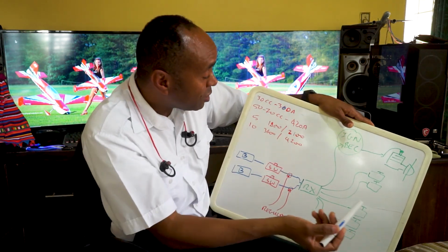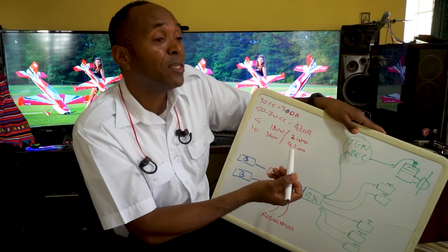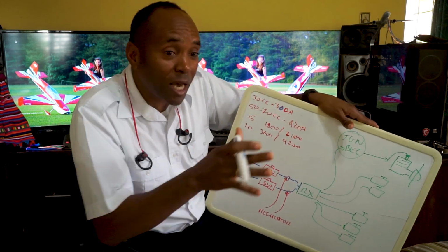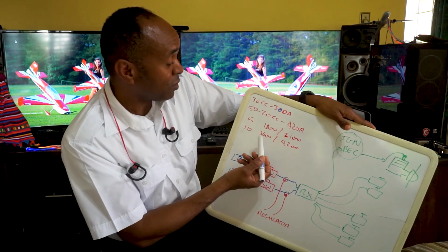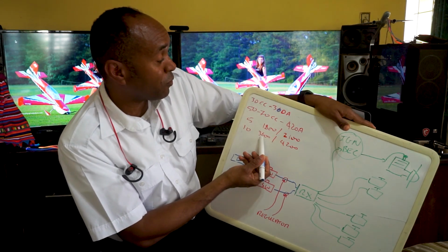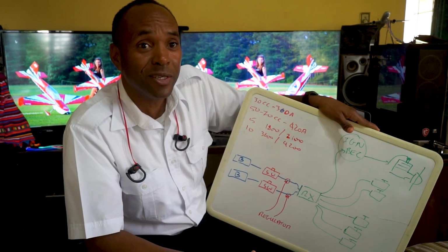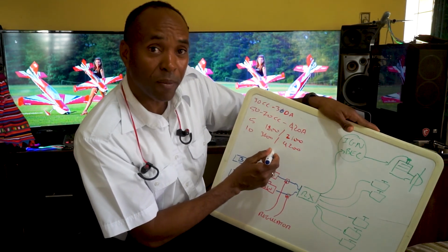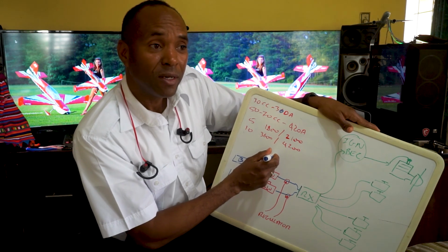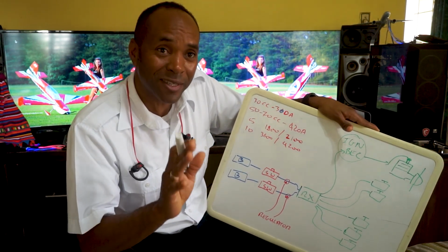With a 70cc airplane it will be 2100 milliamps for 5 flights. If I decide I need enough capacity to do 10 flights, this is the minimum amount of milliamps: 3600 for 30cc, 4200 for 70cc. Now this is your benchmark figure.